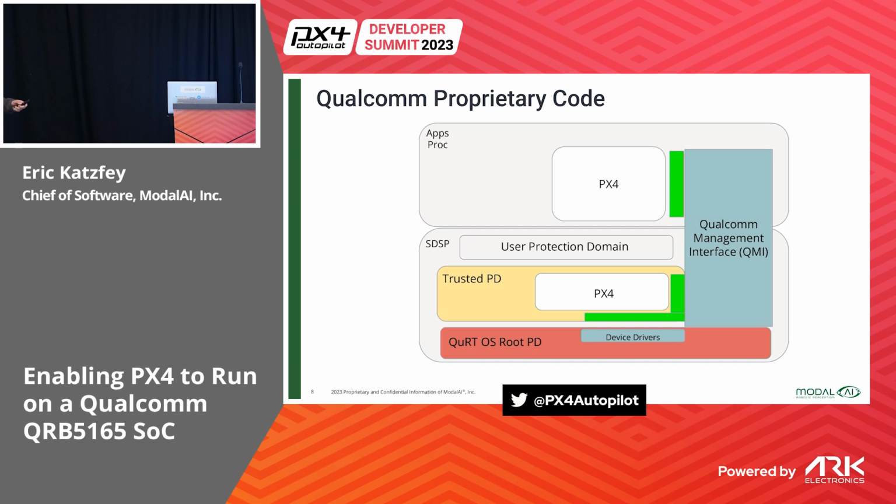If you look at the DSP architecture, the way it runs is fairly sophisticated, and it has different protection domains in it. Similar to Linux, even in NuttX you can have a protected area and then more of a user area. So they've split it up into three different layers. There's the OS layer, and when we build this whole image, we don't even get the source for that. That's just binary, and there are APIs to use it, but we don't have source for it.